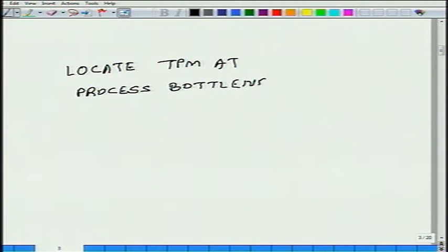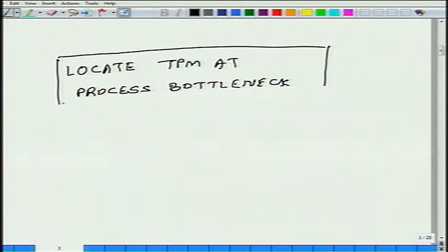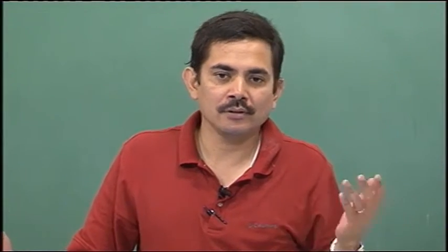Why do we do it? To minimize the back off, so that the deviation from the constraint limit is as small as possible. We have already seen, once the location of the throughput manipulator is fixed, the rest of the control system follows automatically. Level control, temperature control, pressure control, composition control. Yes or no?